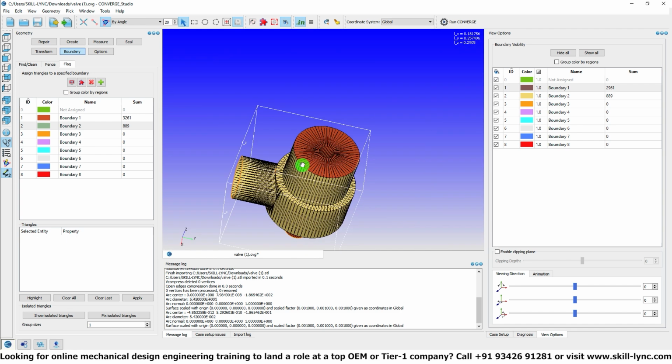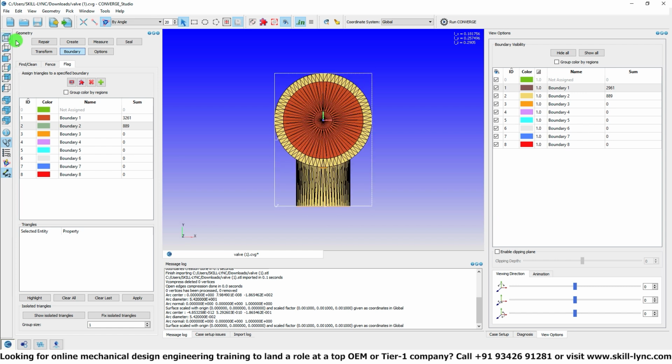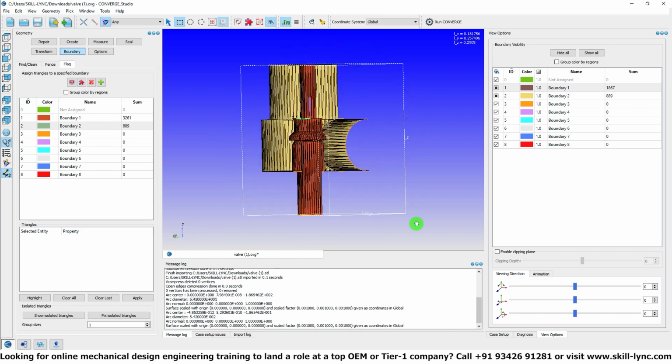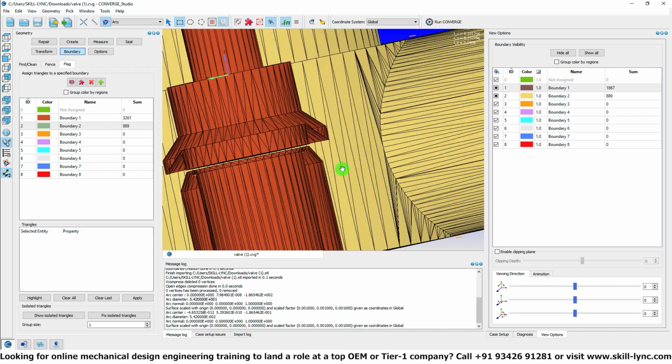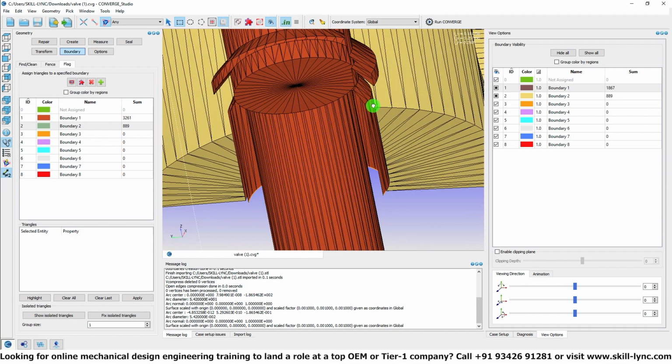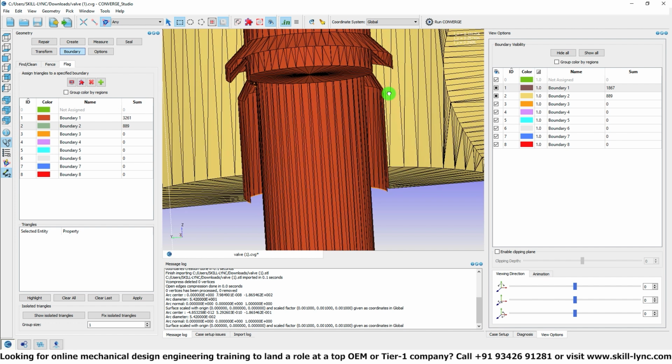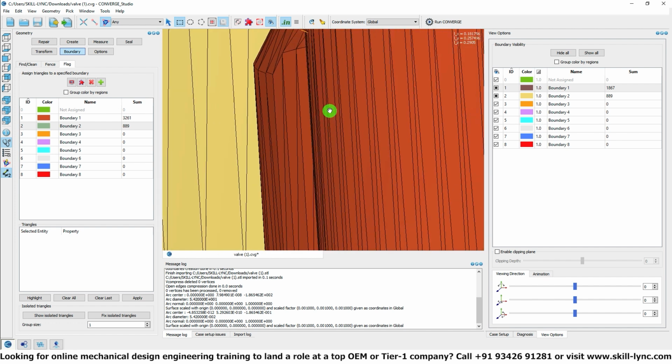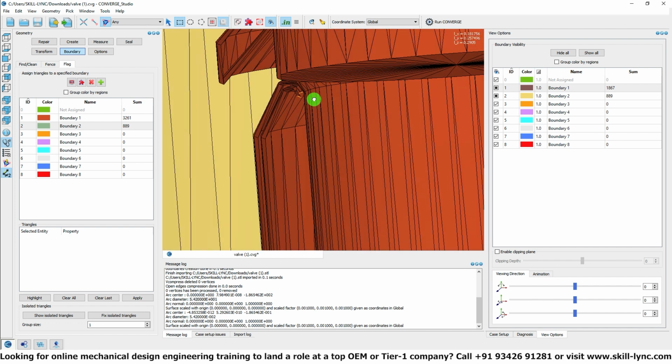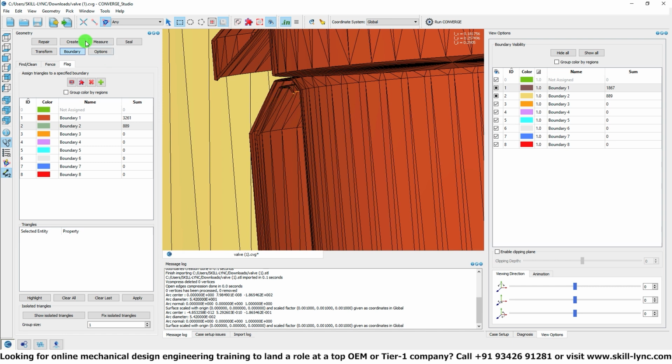So now what you can do is you can look at the geometry from top view, draw the box one more time, use Ctrl H and see if this actually makes sense, right? And the cut view can also help you figure out which components need to be deleted out, right? So here you can see that there is this open edge, right? And this basically belongs to the solid.